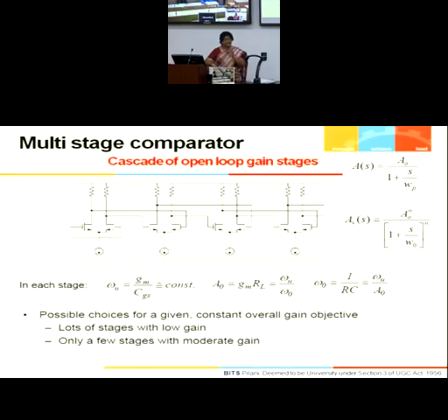Okay, so how to find that omega naught for n stage? If I say I am putting a differential pair as a comparator and it is an n stage amplifier, then for simplicity I am just repeating that amplifier once again for n stages. I am not doing anything else. A simple differential pair, I am repeating it n times in a cascade. So every amplifier will have the same frequency response because they are identical stages, because I am repeating the same stage for n stages.